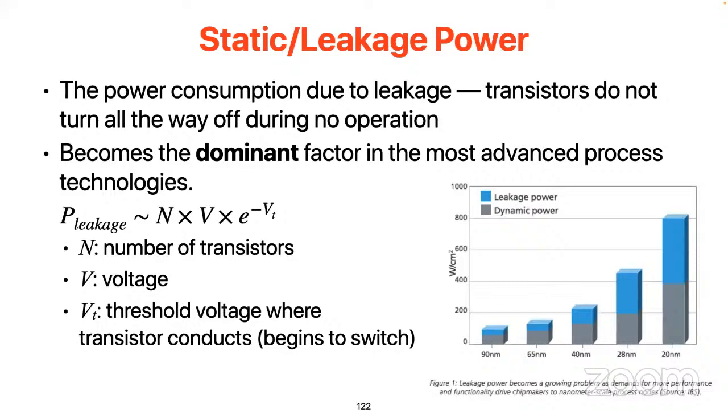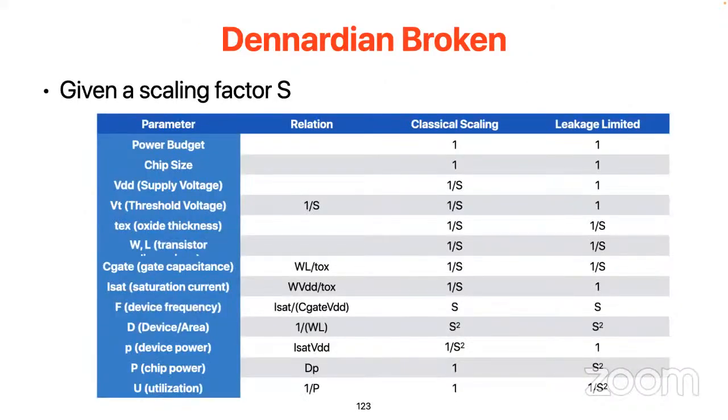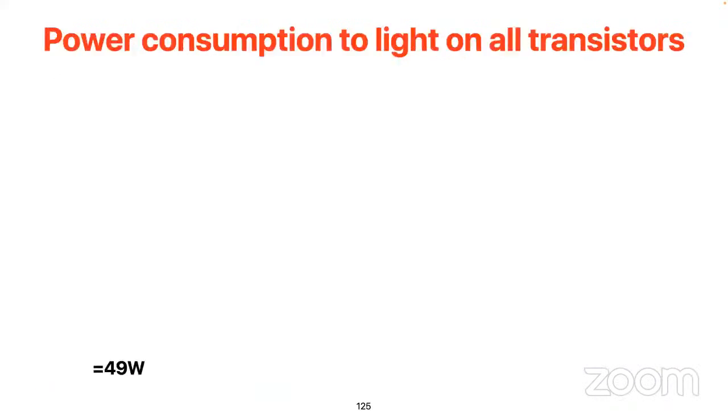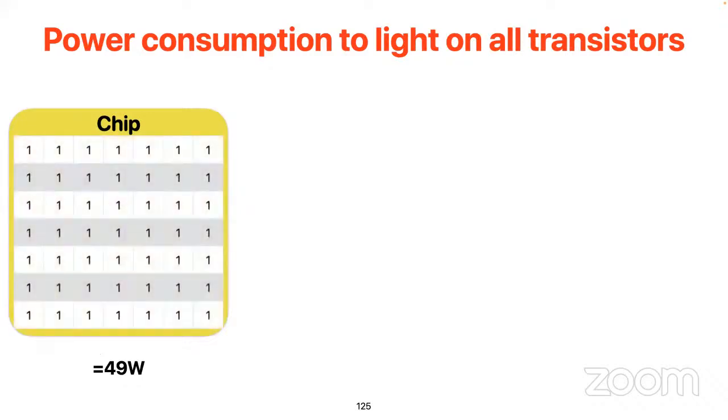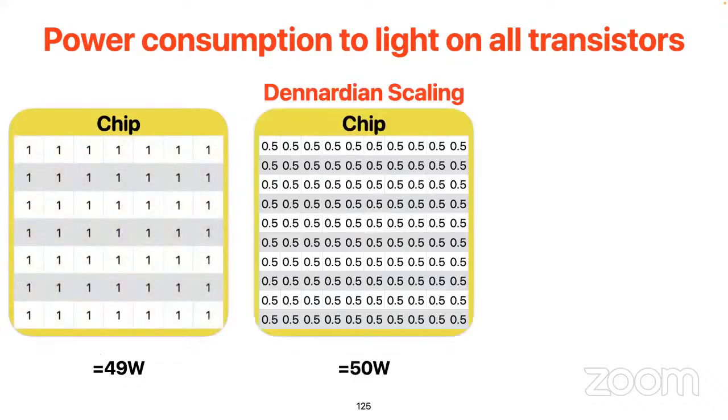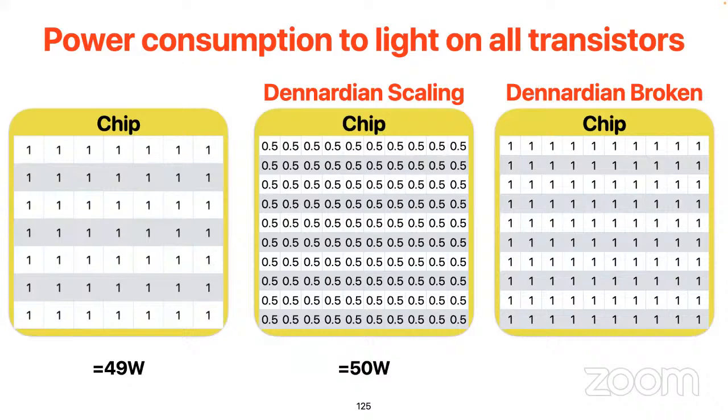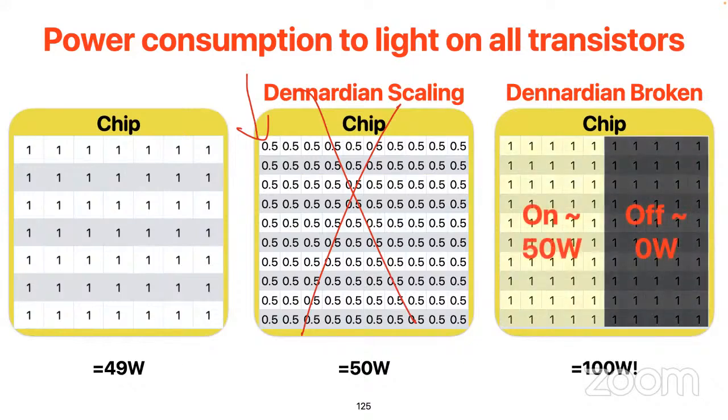So that's why we start to see a lot of solutions to deal with that. And in fact, this trend is causing a problem called dark silicon, because the transistor power is not decreasing as it used to. So it turns out that right now, if I can only power on the chip with the same amount of power, a lot of my circuit could not be functioning.